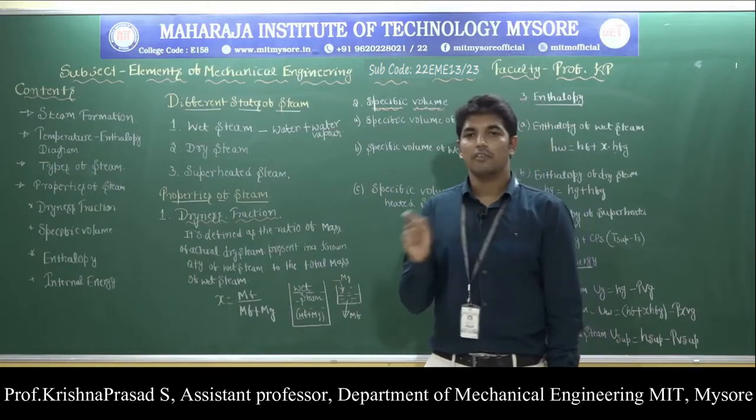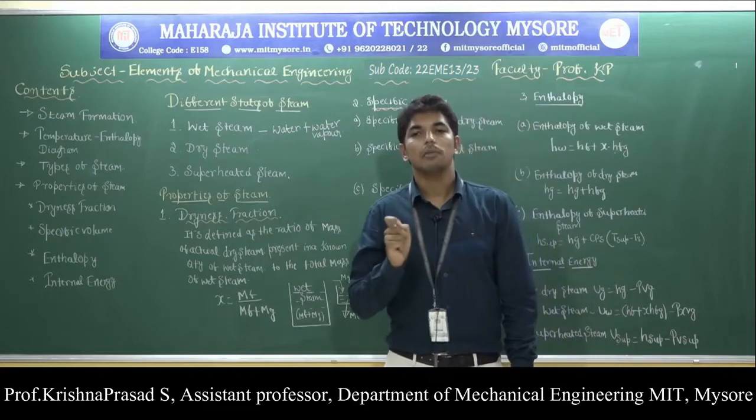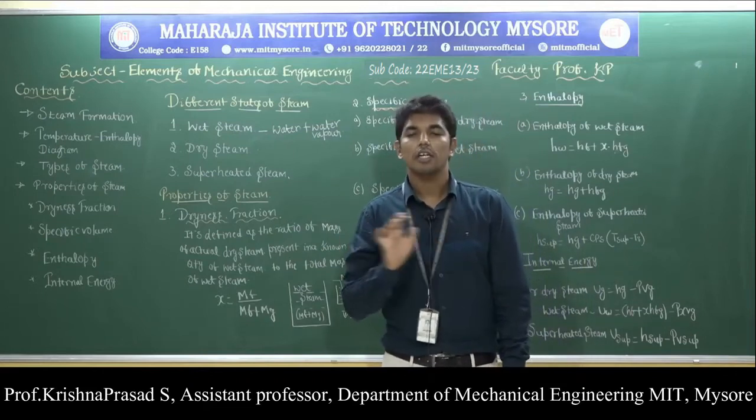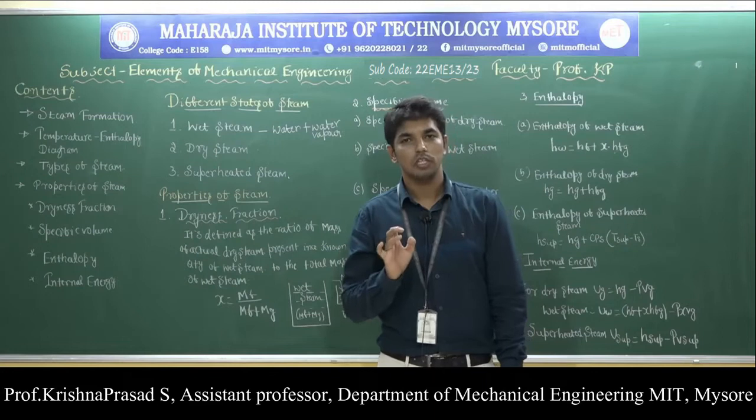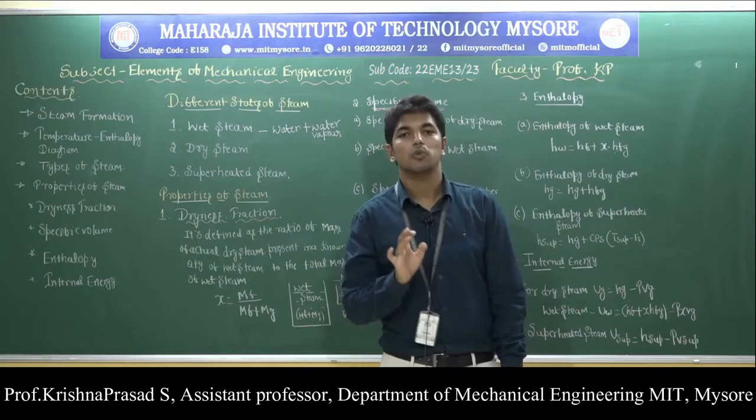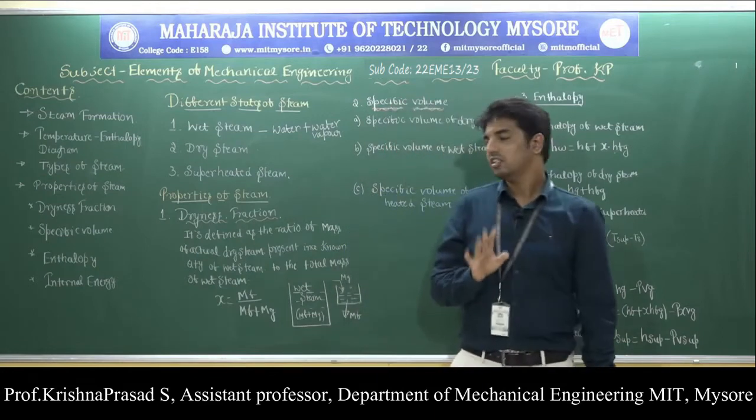So the dry steam is defined as steam which is present completely in a pure vapor form and does not contain any water particle in its suspension at the saturation temperature corresponding to the given pressure. That is called the dry steam.